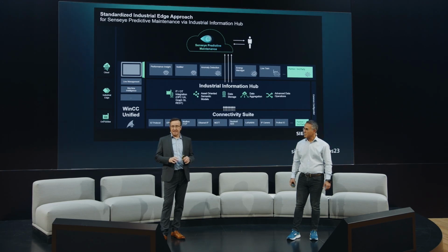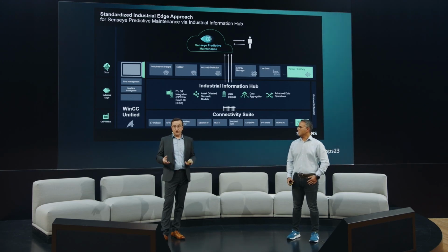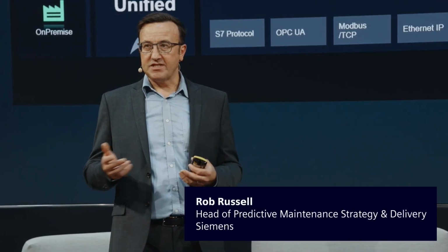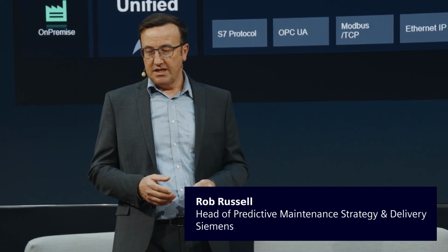And once we understand that normal baseline, then we can start to identify if there's unusual behavior, like spikes in torque parameters or vibration levels that are increasing, for example. And this is all indicative of a degradation somewhere in the machine that's unexplainable. We also combine that with input from the user and feedback, as well as bringing together maintenance information and maintenance records.